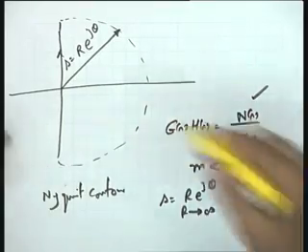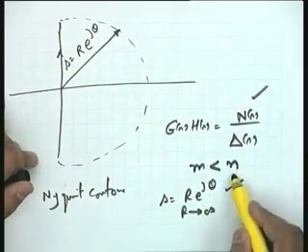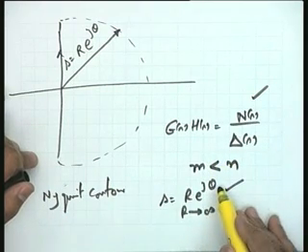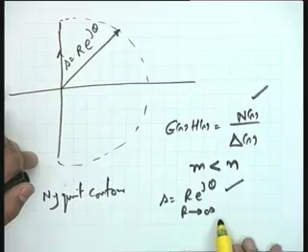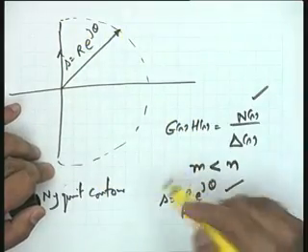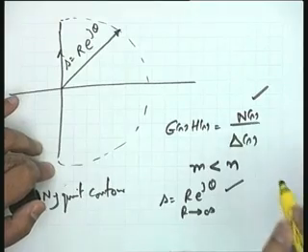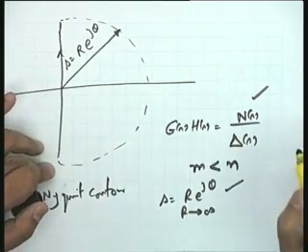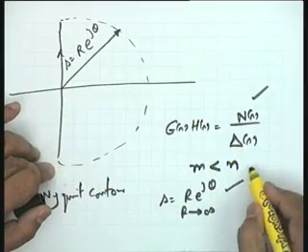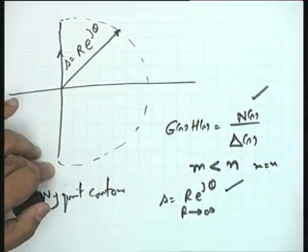Please see, for any point s, since n is more than m, in the limit s equal to r e to the power of j theta while r tends to infinity, this entire infinite semicircle maps into a point 0, the origin of the GsHs plane. Now, if m is equal to n, you can identically follow this.